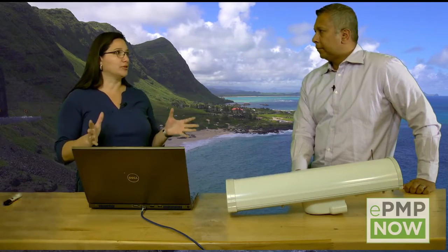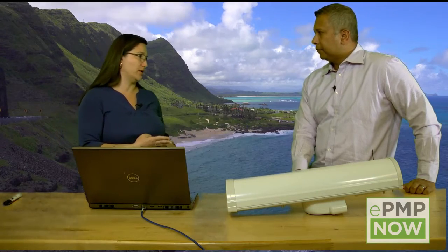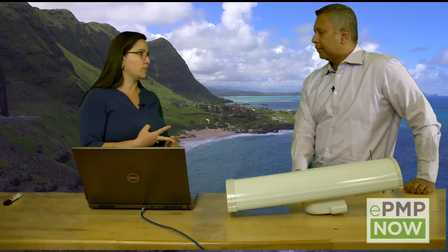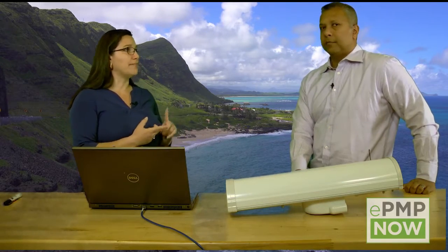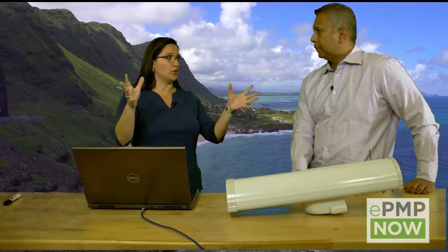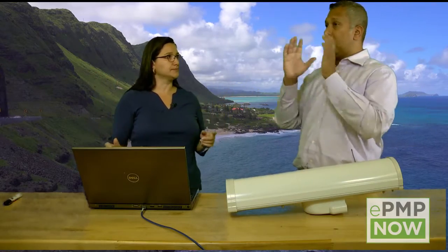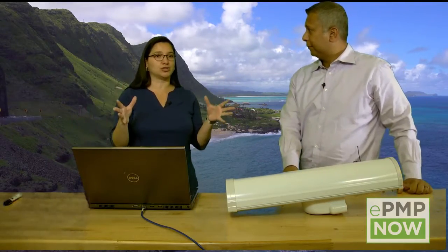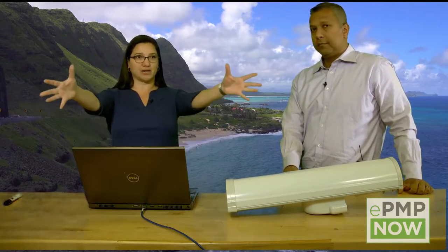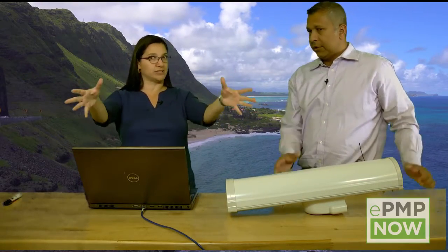And when you talk about directional antenna, there are really three things you look at: the main lobe, the side lobes, and the back lobe. So the main lobe is where you want your energy to go, the one in front. Is that me talking in a certain direction? Yes. So this is my main lobe, my voice, mouth is here? Exactly. Okay. So if you imagine this location is your access point and all your subscribers are in front of you, this is your main lobe of what you want to illuminate because you're talking to the subscribers. This is the most energy I'm sending in that direction. Yes. Okay. And the better the antenna is, the more energy you send in your desired direction in front.